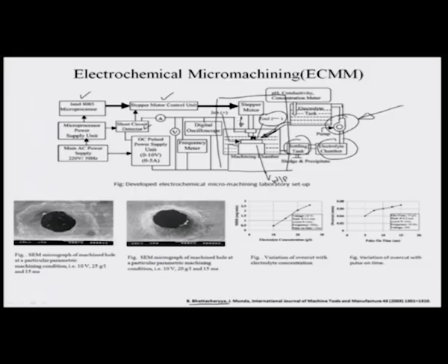There is a short circuit detector, there is a DC pulse power supply, and there is a measurement frequency meter which monitors what is the frequency at which the pulsating is happening. The digital oscilloscope to monitor the signal as well, okay. And then there is of course a microprocessor power supply unit which controls based on the gap current the distances between the tools and the electrode.